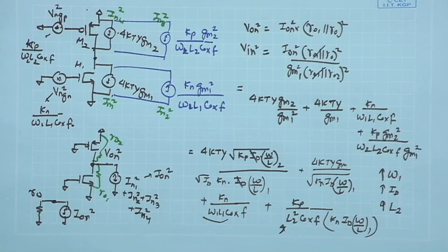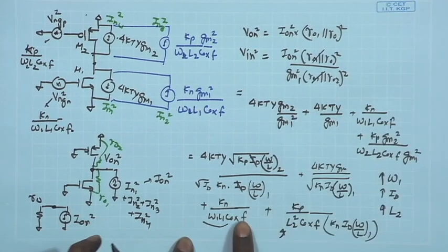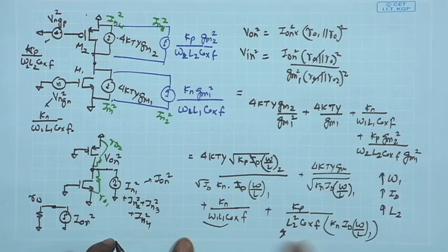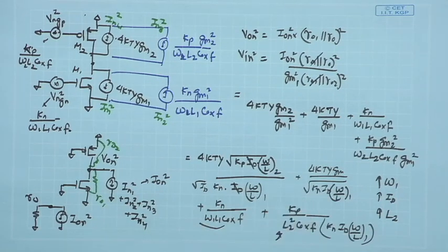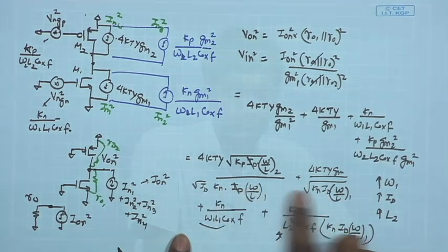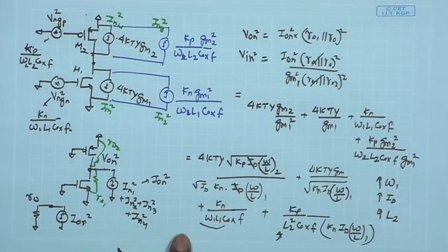And another very important concern happens to be the 1 upon F noise corner that we have discussed. So, as we see, the 1 upon F noise term over here will go on increasing as we go towards lower frequency, whereas the thermal noise floor is constant.